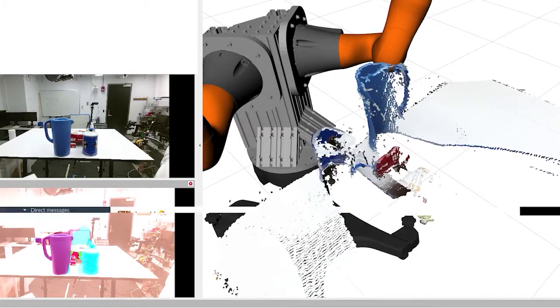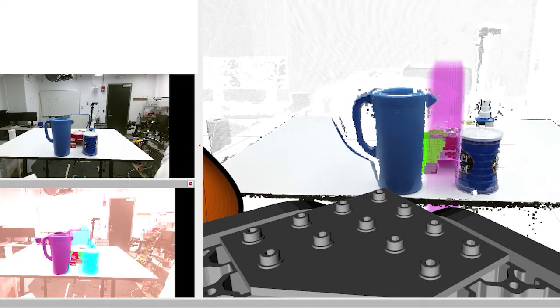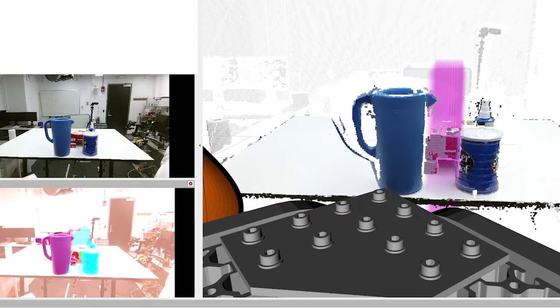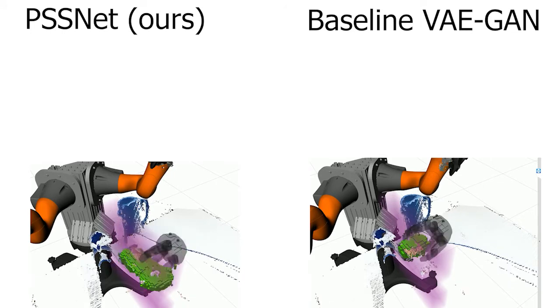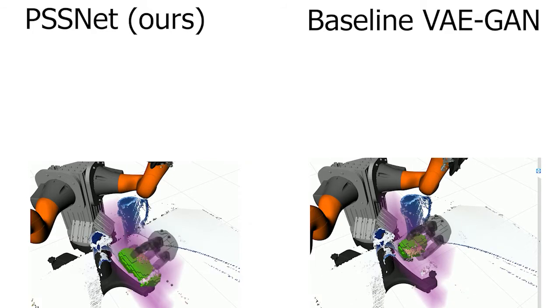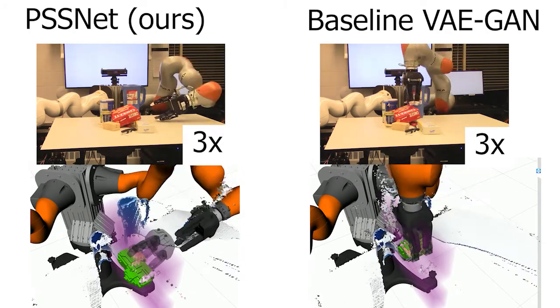We set up another scenario for grasping the YCB Cheez-It box under partial occlusion. The segmented Cheez-It box is used to construct known occupied and known free space voxels in the visible slit. Our plausible shape sampling produces diverse samples, and we are unsure if a top grasp will be successful. We attempt the better side grasp. Using the baseline with low diversity and incorrect completion, the top grasp appears valid for all samples, but fails when attempted.